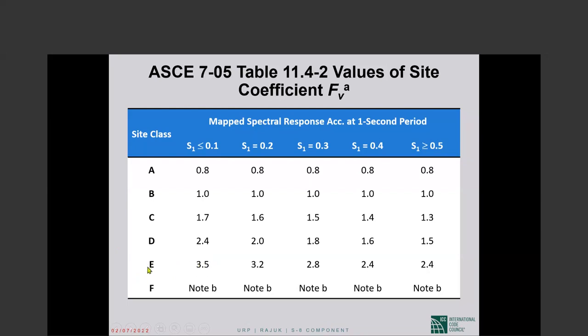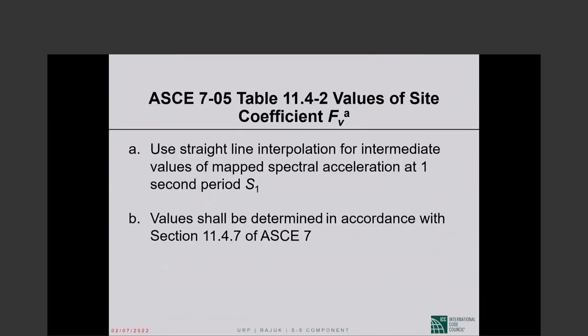But on the same soft soil, if the ground motion is strong, as would be the case in high seismic areas, then the amplification is lower. Okay? So lower intensity ground motion would be amplified to a higher extent by overlying softer soils, but high intensity ground motion would not be amplified to the same extent. This tends to be quite important.